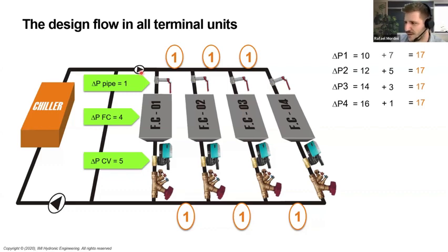Okay, here it is. Notice that as we get closer to the pump, the pressure drop increases. It means that this valve here will have to create more pressure drop because there's more excess of available pressure. Okay, this is the math behind the balancing. I know that when we are in the job site, we are not doing these calculations. We don't know how much pressure drop we'll have in a segment of pipe, right? Doesn't make sense. We have our own methods to figure it out, but this here is just the math behind it. I know some people try to balance on their design, which is almost impossible, right?